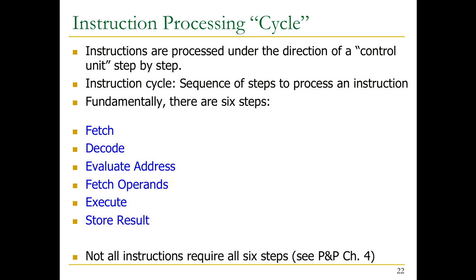You fetch an instruction, you decode the instruction, figure out what it is supposed to do. You evaluate the address of the instruction. For example, for a load, you evaluate the address. You fetch the operands. You basically, for example, fetch from the register file or memory, depending on the instruction type. You execute the instruction. ALU operations have that execute stage. You store the result. Not all instructions, of course, go through all of these, right?